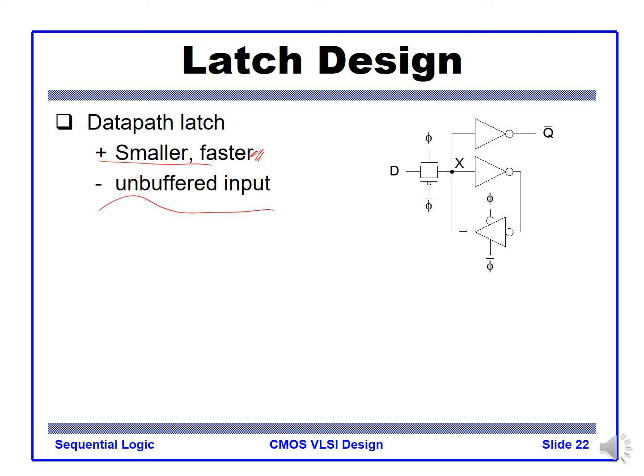So the timing, the data edge behavior in this implementation is very sensitive to input loading condition or input driving strength that affects the waveform on the X. The behavior is very sensitive, similar to output load variation. So without buffering, the driving buffer state or wire capacitance affects the behavior of this latch design. So this is not good in general.